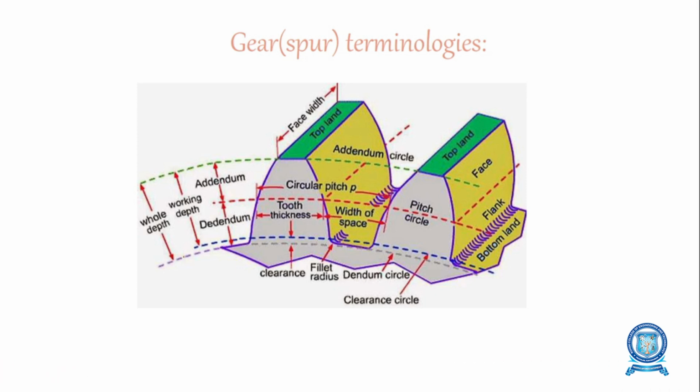A helix angle is an angle between any helix and axial line on its right circular cylinder or a cone. The typical range of a helix angle is about 15 degrees to 30 degrees. Likewise, lead angle is the angle between the tangent to the helix and the plane perpendicular to the axis of a cylinder.